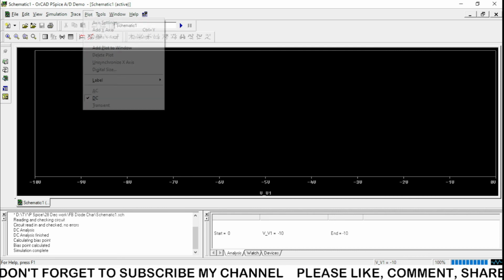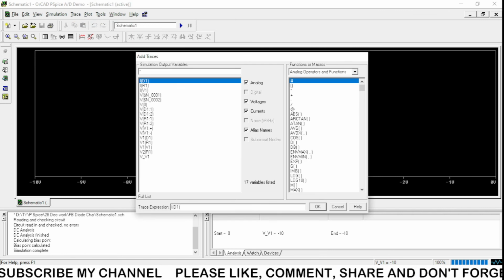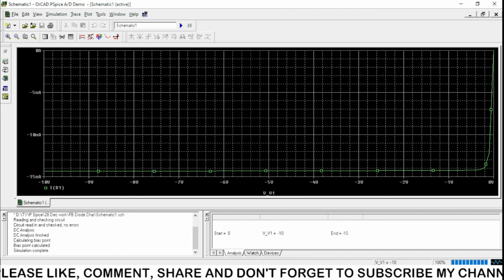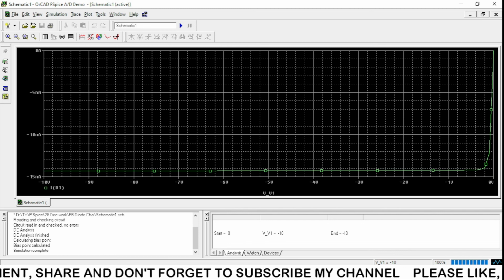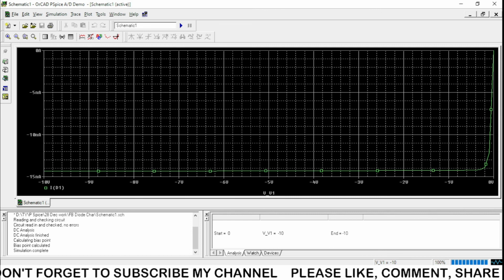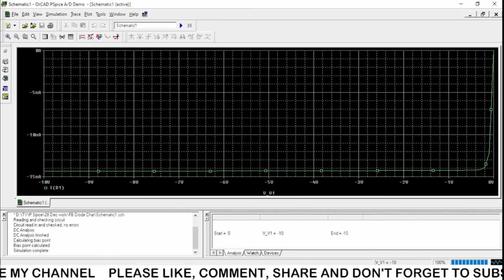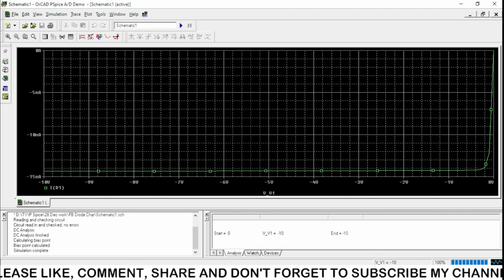We have to add the trace. So trace, add trace, ID1, we have to check the current only. So this is the current. So you can see this is a third quadrant. Actually you can see this is a 0 and this is a 0. So current that is starting from this point and it will come towards this point, and then it will be independent of the applied voltages. So whatsoever the voltage, maybe -1, -2, -3, -4 up to -10, the current will remain as it is. So this is called a reverse bias characteristic of a simple PN junction diode.